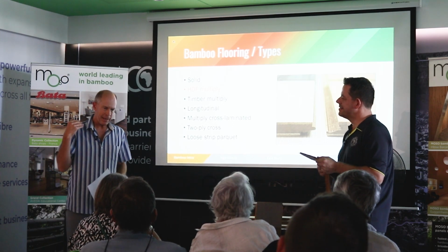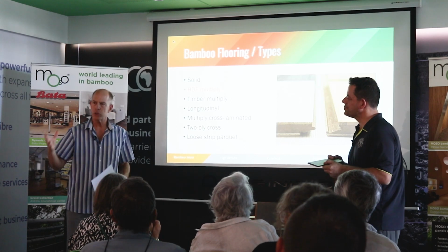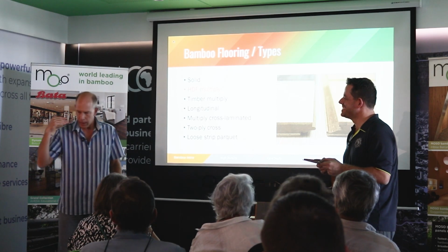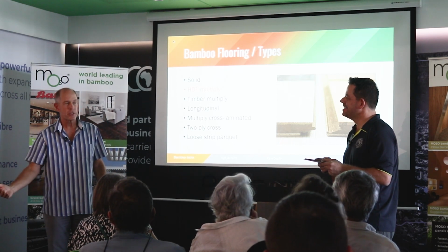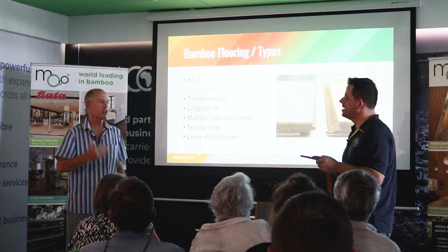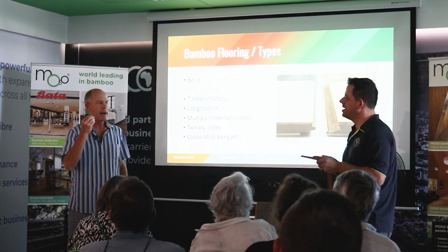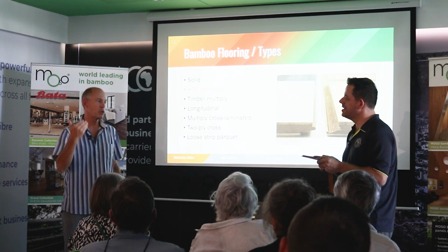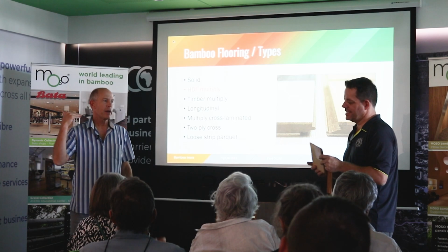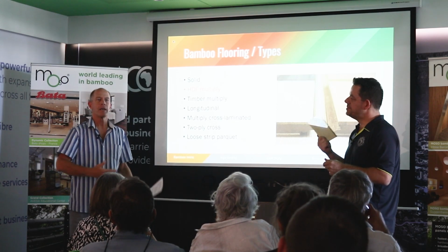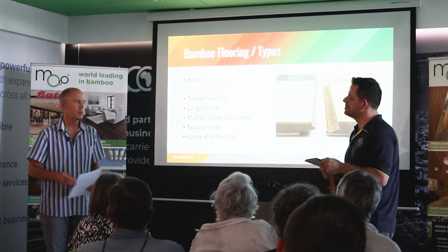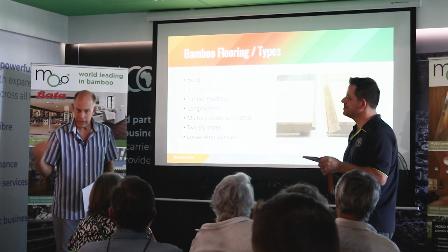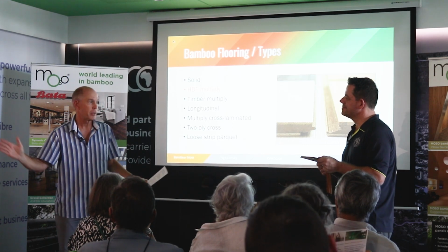So again, it's a good floor depending upon what you want it for. You probably wouldn't put it in a railway station, but for a domestic situation, it can be a really good cost-effective flooring. As with laminate flooring, the HDF core is susceptible to damage if there's excess moisture, big spills, and that kind of thing. So you've got to know the flooring, how to look after it, but in the right application and treated and installed in the right way, you've got a floor that'll last for 30 years plus.